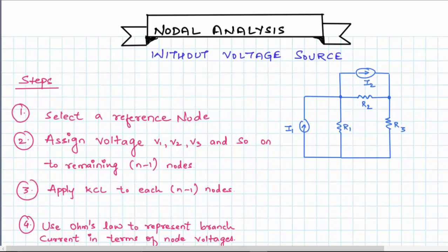In this lecture, we will start with nodal analysis, and later in this section, we will talk about mesh analysis. Nodal analysis provides a general procedure for analyzing circuits using node voltages as circuit variables. Choosing node voltages as circuit variables instead of element voltages is convenient and reduces the number of equations.